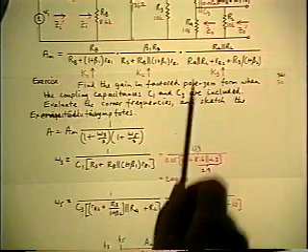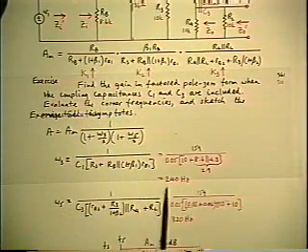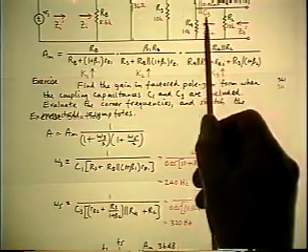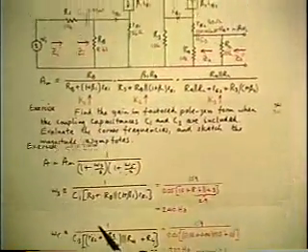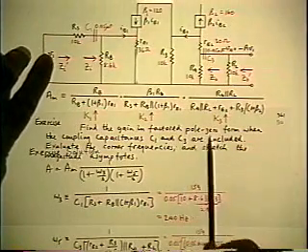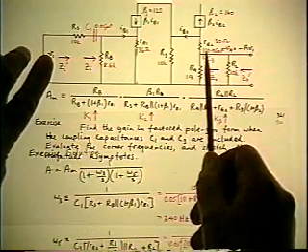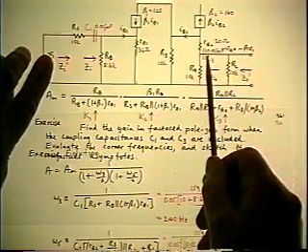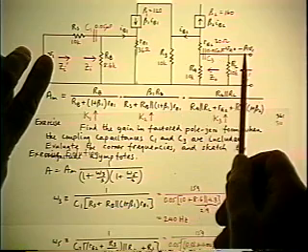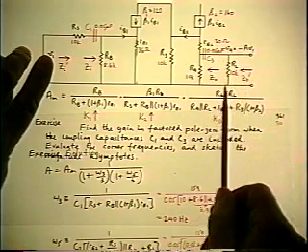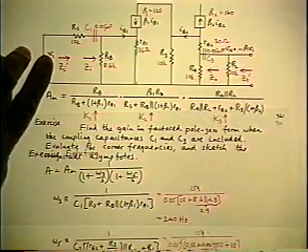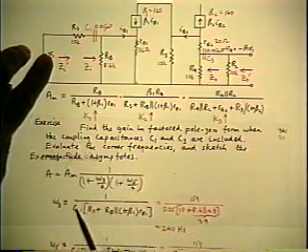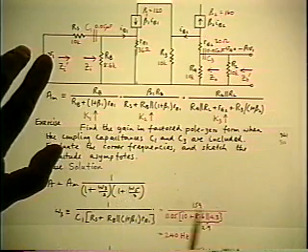Together with the C3, that gives you the inverted pole omega 5. To check that the Rn is infinite, restore the V1, replace the C3 with the independent source, adjust them to null the output, propagate the null back. Immediately, if there's null at the output, there's no current in RL, no current through the second source. Rn is infinite, and there is no inverted zero to go with the pole.